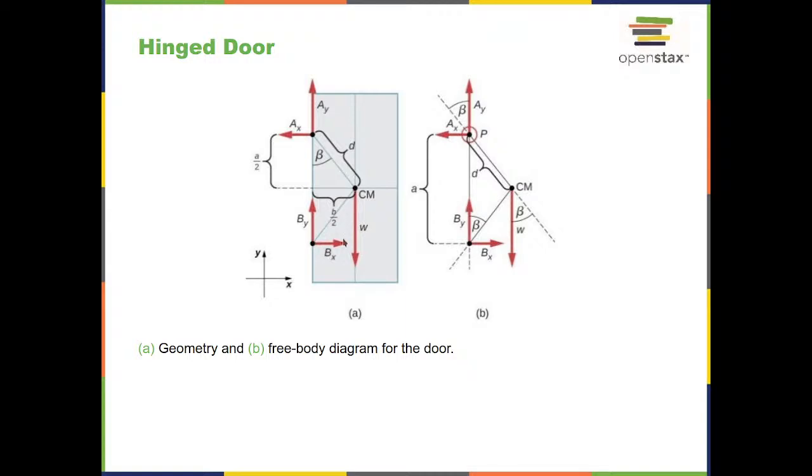So the horizontal component of the force, the x component of the forces, will have to add up to 0. So that means that AX and BX have to be in opposite directions, or of course they could be 0. But if they're 0, then of course that doesn't work with the condition for the torque. I hope that explains things.